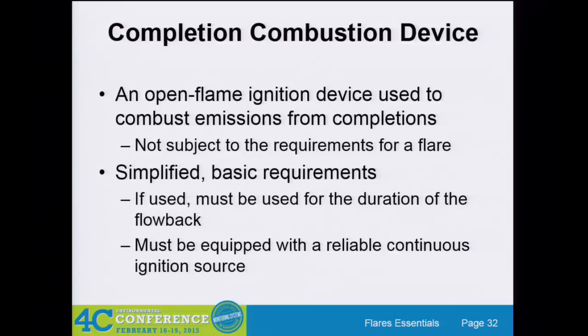That's from a flare that's not lit, and it's basically a stack. So the EPA has been petitioned and commented to please allow spark ignition, and right now, today, they just don't trust the technology. They basically think that if you do not have a flame present at all times, you're going to have a stack out there sooner or later and not a flare or a combustion device.